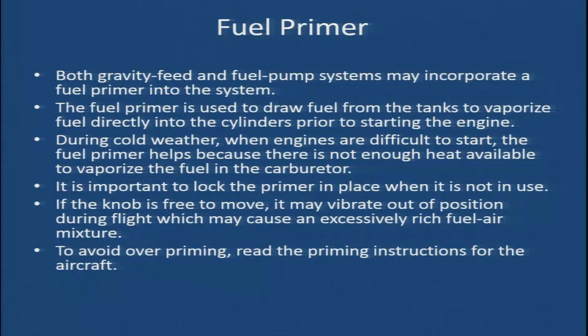So, next is fuel primer. In both the gravity feed and the fuel pump systems, fuel primer is used. The fuel primer is used to draw fuel from the tanks to vaporize fuel directly into the cylinders prior to starting the engine. So, before starting the engine, this fuel primer is used to bring the fuel from the tanks to vaporize it directly into the cylinders just before starting the engine.